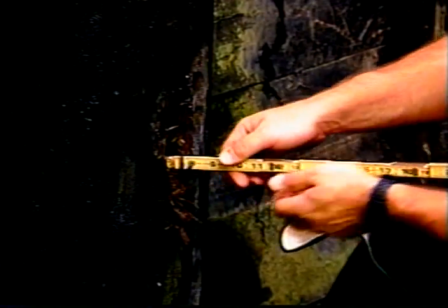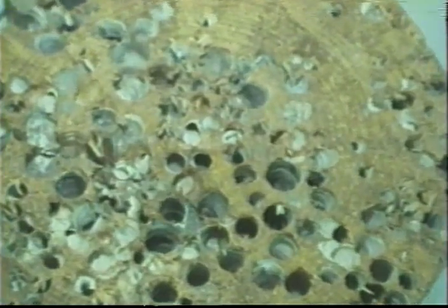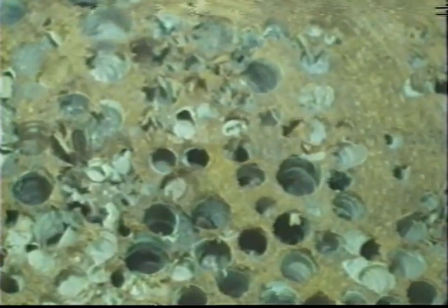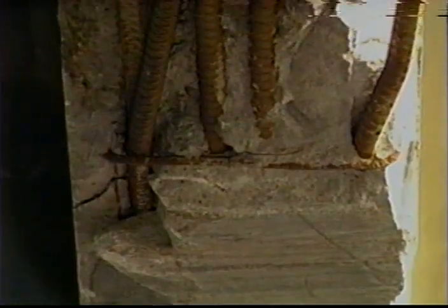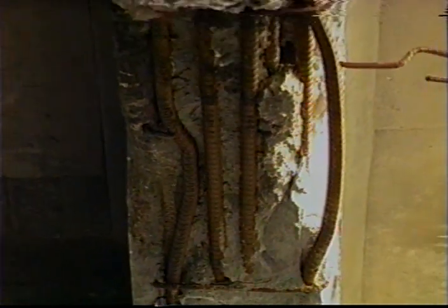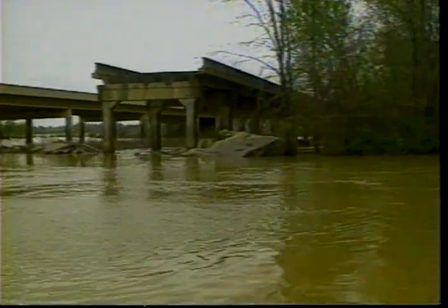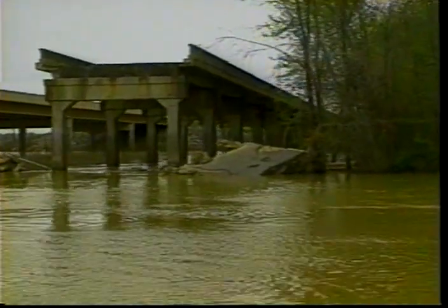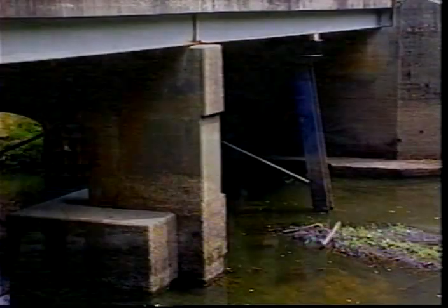Decay is caused by the penetration of moisture. Insects and marine borers weaken the structural strength of the wood. Condition ratings can also be affected by mechanical damage due to collisions, water erosion, and scour. Bridges may be struck by vehicles or by ships. These accidents can result in serious damage and even complete collapse of the bridges, causing loss of property and life.